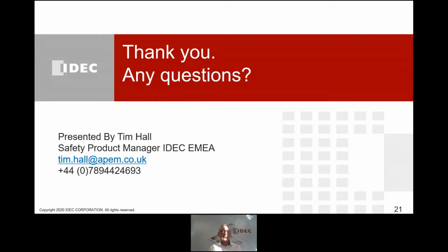Yes, you do. The Machinery Directive has instructions which say that if you provide equipment and place it into service, it shall conform to the Machinery Directive. Emphasis on service and not sale. If it is in service, it's deemed to be in the marketplace. And the reason that's a concern is because next year we could sell that machine. And if that machine goes into the open market, it has to have a CE mark on it. So you have to go through the CE marking process, do the risk assessment, look at your safety requirement specification, do your design verifications, and follow the cycle.